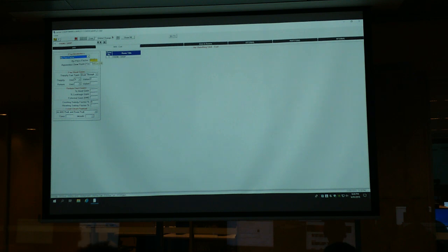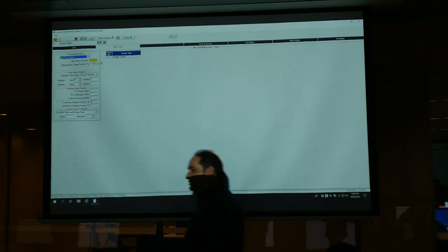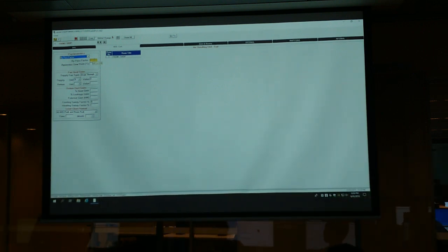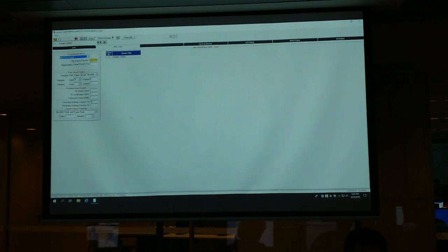I think 15% is all right, but it's a little bit high. Allowed, yeah, but 10% would be better, because we know a greater bypass factor just means more air bypasses the cooling process. It's less efficient.